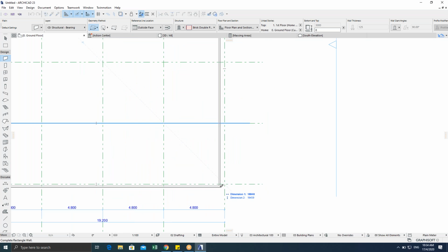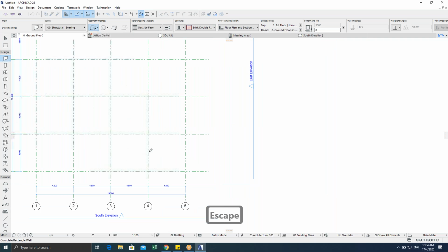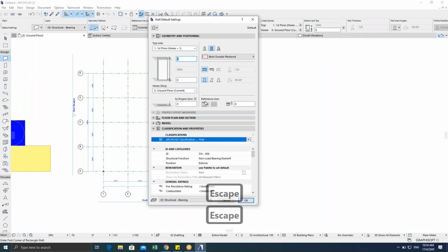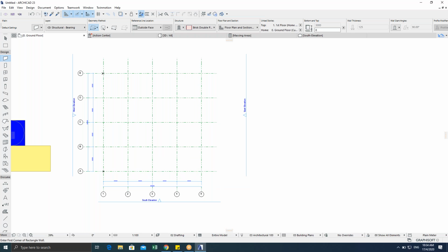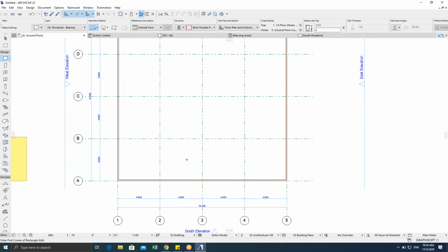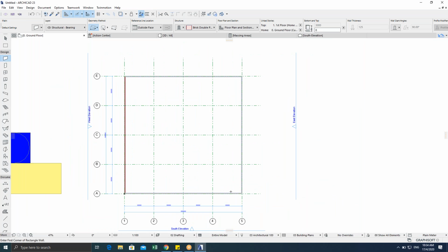Before that, I forgot to say, wait. Double click the wall again. Make sure you choose core outside face. After you choose that, click OK and repeat again. Just click from here to here. Okay, try to do that first, guys. Let me know if you have already done it.